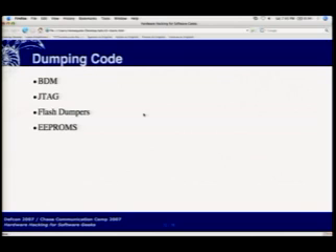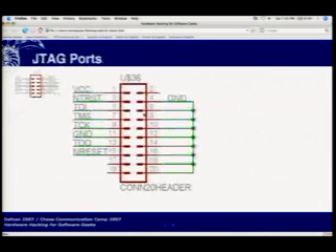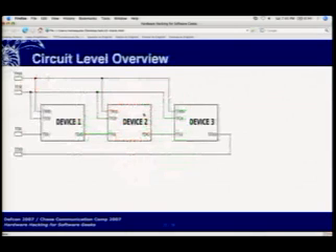Basically, the JTAG talks to a chain of shift registers that sit between the actual metal pin on the outside of the circuit and the silicon inside the device, and allow you to change the pin states without the chip itself actually running. These are a couple of JTAG pinouts, and this is the shift register. I'm going to go over this more in the Q&A section.